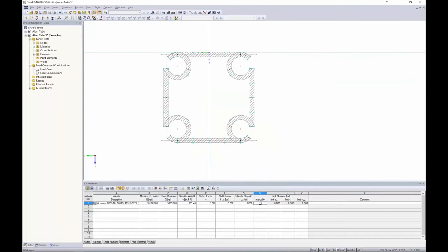So essentially that's all that we have to do to create this custom thin-walled section. Now, if I'm ready to calculate my cross-sectional properties, I can go up here to show results. The program says, okay, should I start the calculation? Yes, and immediately I get an error saying FY is not positive. Please check this in the table.